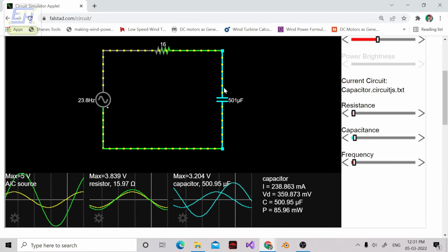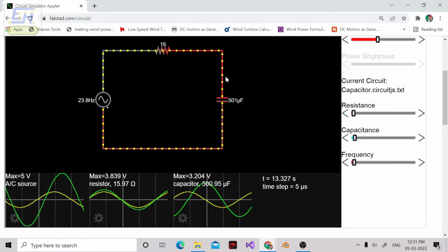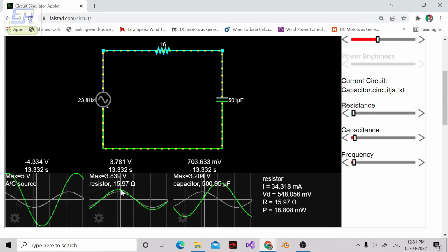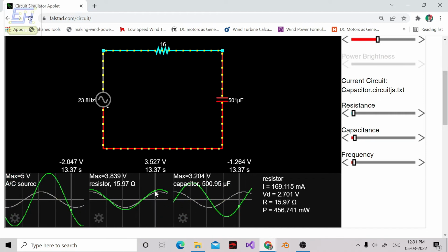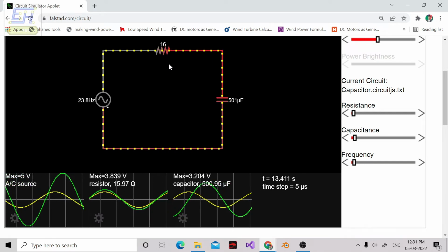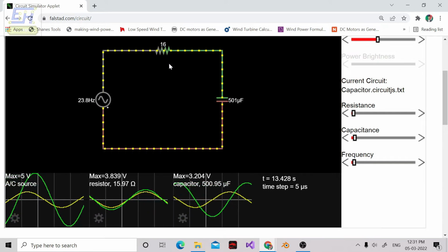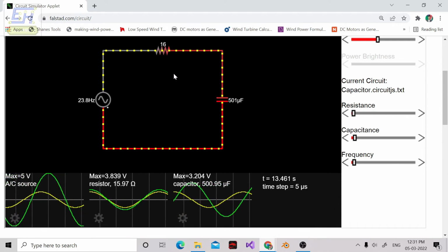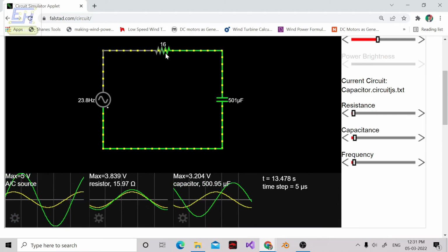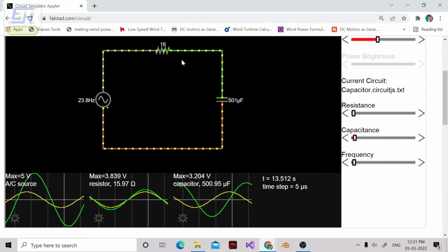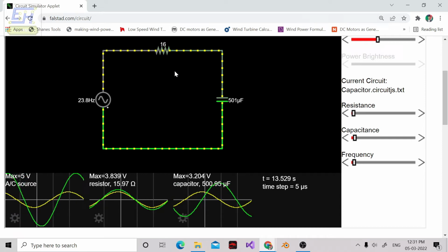Another point to note is that the resistor, irrespective of the frequency provided to it, irrespective of the number of components and their values connected to it, will always be in phase. The resistor's current and voltage will always be in phase, because a resistor is a frequency independent element. It is the most basic element, so resistors are very ideal to measure circuit parameters. What you do is simply connect a small resistance in parallel or series in the circuit in order to measure the parameters specifically in AC circuits.